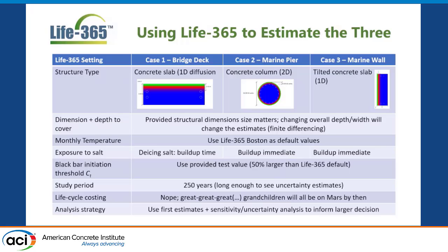Provided structural dimension size matters, where one of the weaknesses of Life-365, and you get lots of technical support questions on this, is: use an 8-inch slab with a 2.5-inch cover. You get a service life, let's say 25 years. You go back and change the depth of the slab to 16 inches, still with a 2.5-inch cover, and you're going to come up with an answer of like 30 years.